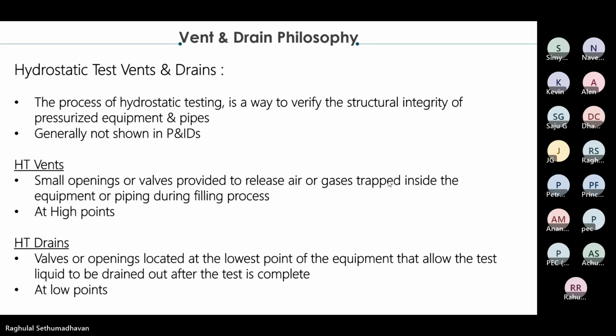These are generally located at the highest point. The vents will be located at the highest point of the equipment to allow air to escape when we are filling the test medium. Similarly, hydrostatic test drains will be located at the lowest point so that we can drain out all the hydrostatic test medium after the test is done.